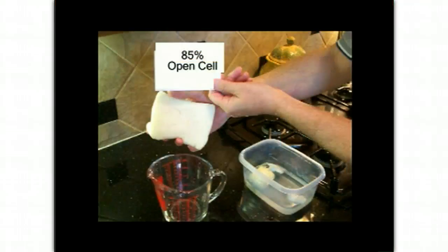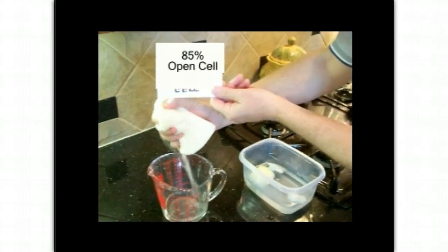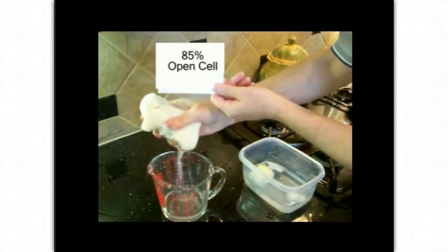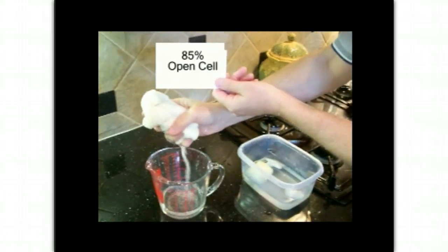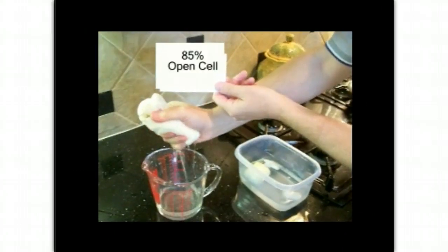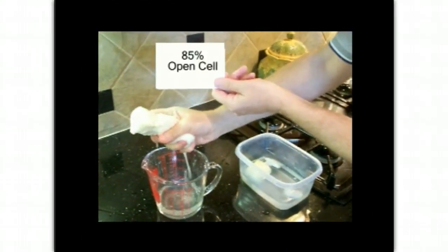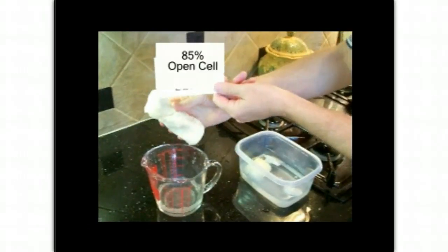For example, this video clip reveals the amount of water absorbed by a wall insulation product. The experiment shown here demonstrates that many products intended for wall and roof assemblies could absorb much larger amounts of water in contrast to the data sheet, which indicates that it is a non-absorbing product. If there is a water leakage through the water-resistive barrier, the use of this material in wall cavities could create massive mold problems, since the normal wet-dry cycling will not likely occur.